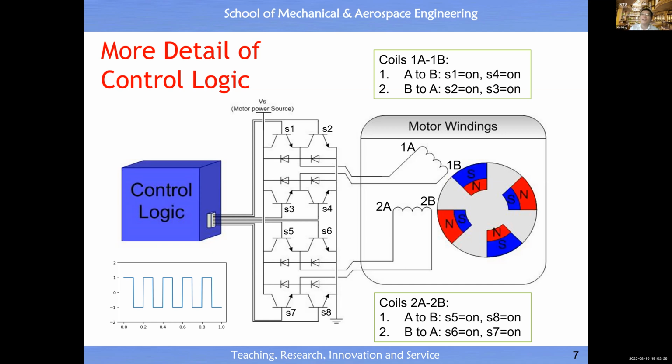That corresponds to the duration of the motor in one rotation, in one orientation, and how long it stays there, right? So these are the simple concepts. Once you know this, conceptually it is quite easy. For one signal line, I just control on, off, let's say 0, 1, 0, 1, with 1 for a certain duration. The duration is required by your application. Let's say I stay there for 10 milliseconds, that's it.